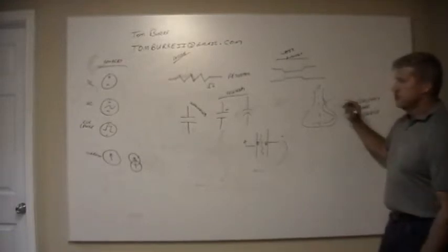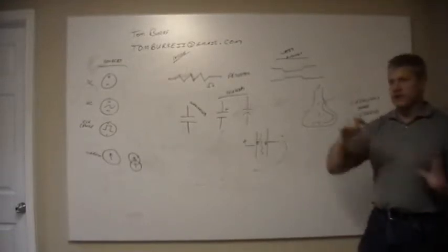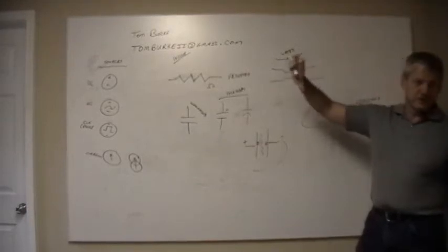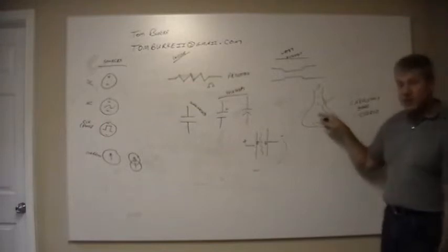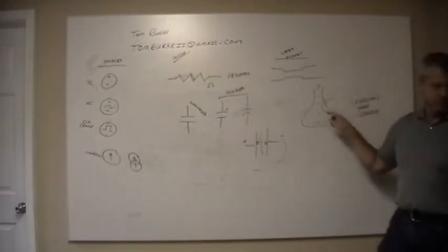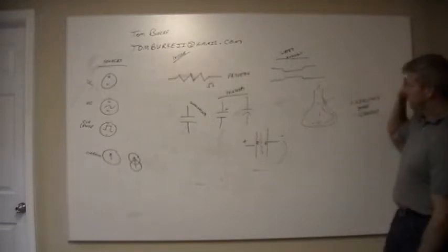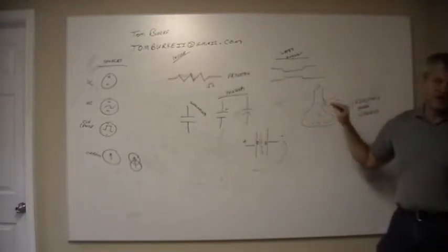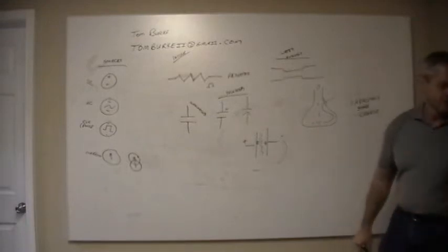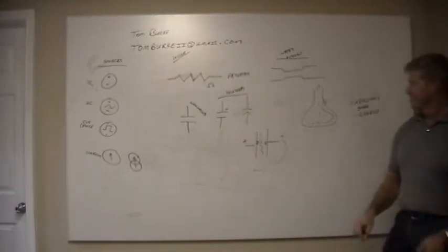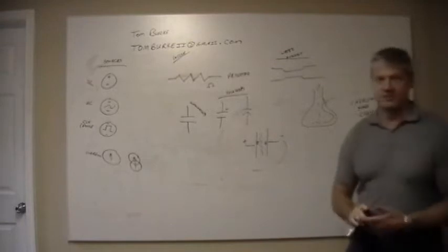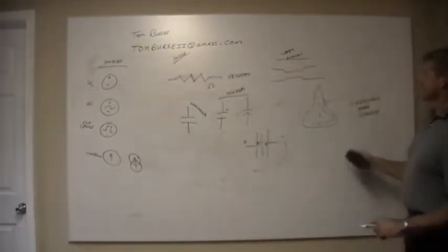The general rule of thumb was 1,000 volts per diagonal inch. So if you had a 30-inch TV, you were sticking 30,000 volts back there. And that tube is a damn near perfect capacitor. It will hold its charge for decades. I've seen people get the shit knocked out of them at 5 or 6 years sitting out on a porch. First thing you always do with a TV tube, if you got one, is you ground it out with a couple of screwdrivers that are connected together with jumper clips, because it will kill you.